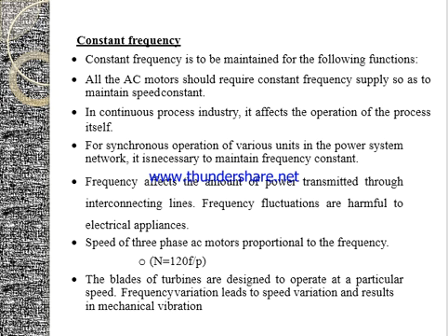Let us consider a constant frequency, which has to be maintained for many different reasons. First, all the AC motors require a constant frequency supply so as to maintain constant speed. In the continuous process industry, if constant frequency is not maintained, it will affect the operation of the process itself. For synchronous operation of various units, absolutely constant frequency is necessary. And frequency will affect the amount of power transmitted through the interconnecting lines.